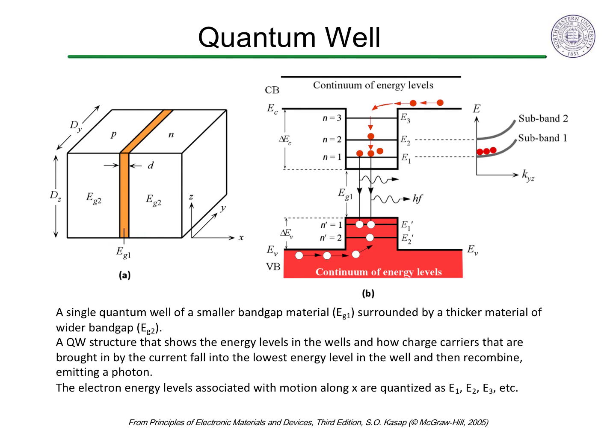These electrons are called a 2D electron gas because they are confined so that they only move freely in two dimensions. Recall that even the n=1 state has energy a little above the bottom of the well. The quantization limits the possible transitions, and so a more narrow spectrum of light is produced. The quantum wells also help trap electrons and holes, giving them time to recombine without continuing into the other region, so that the quantum wells improve the quantum efficiency of the LED.